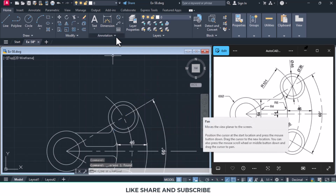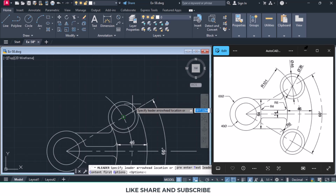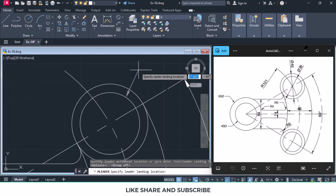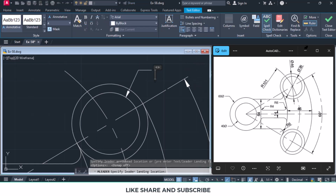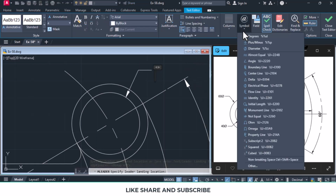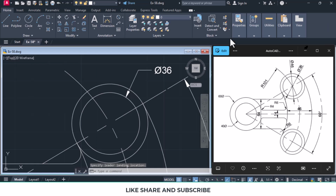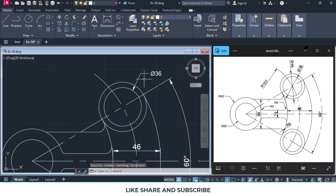So we'll better use the leader, and we'll turn the snap off, and we'll click over here and click over here, and then we'll give the diameter as 36. So in symbol we select diameter, then we type 36 and we say close editor. So this looks more readable.